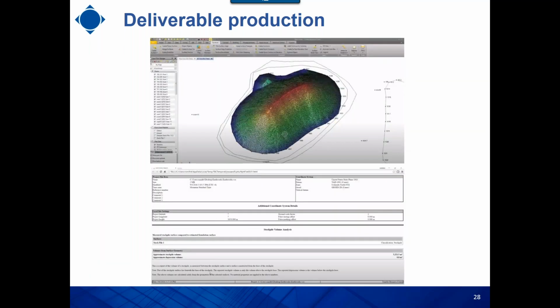You can create a surface from the point cloud and provide the customer with a cut and fill report or volumetric report. These are all the deliverables that you can generate from TBC using the point cloud data, depending on the application and depending on the requirements of the organization that you work with and software infrastructure. You will make those decisions on what software and how they should be used for producing deliverables.